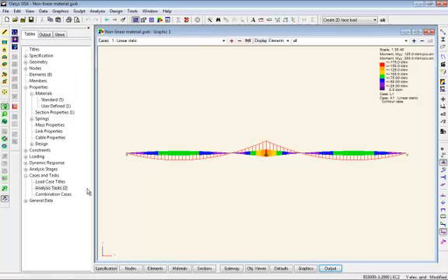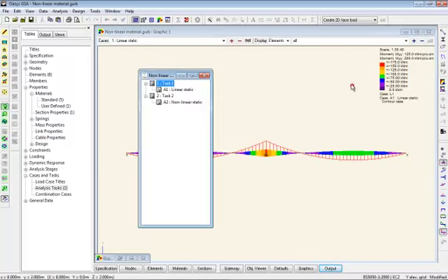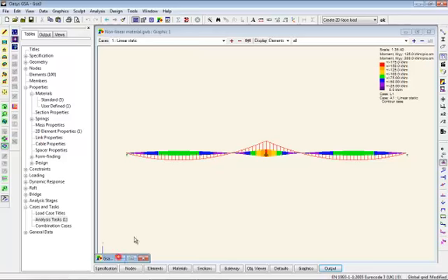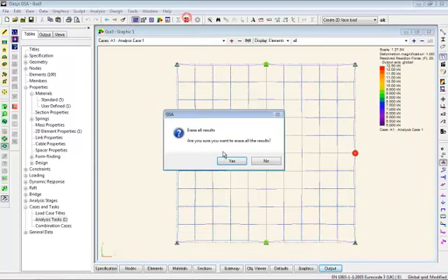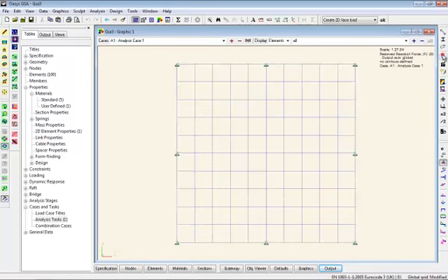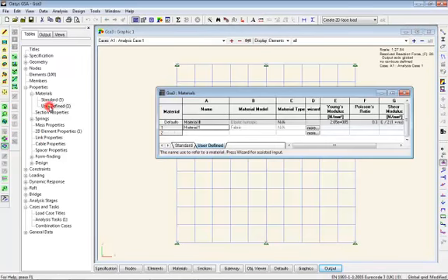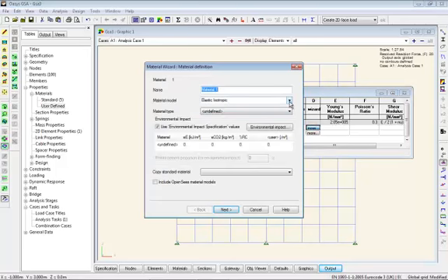Now talk about materials. If I just flip back to this 2D element model, something in the latest version of GSA is orthotropic materials throughout. So what we can now do is I can define, so let's say a timber elastic orthotropic material.